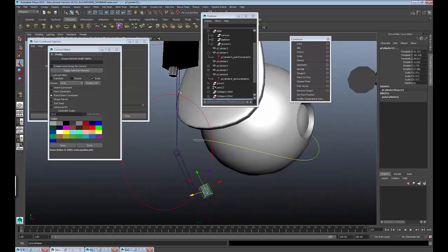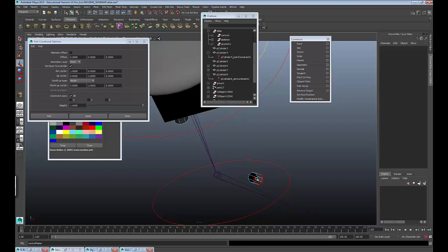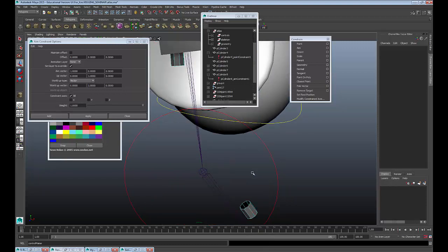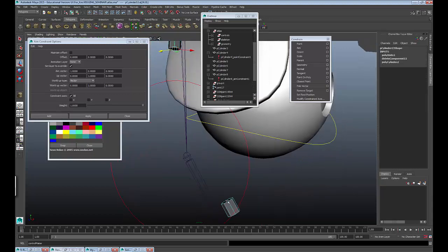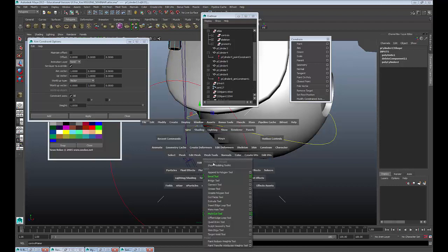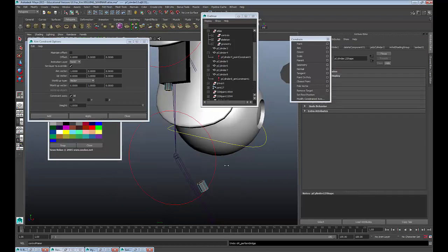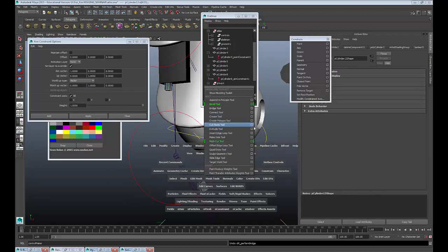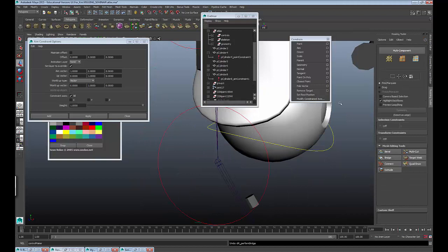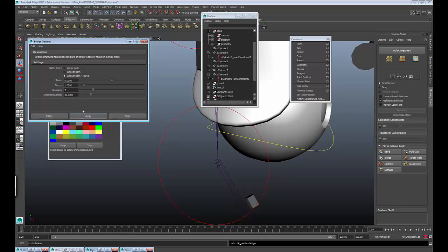All right, so let me just do that. So delete these guys, I'll combine them, and I'll just do a bridge. No, which was that, a linear bridge? Which one was that? Probably a linear. So let me just do it again. It has to reset all my settings. So bridge tool, option box. Oh, that's a different bridge tool. I'm going to use this guy. So bridge, option box.